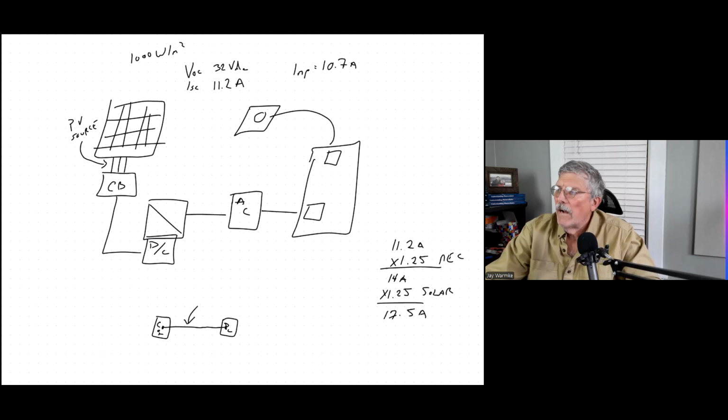Well, it turns out that the panels themselves generally in today's market come with 12 gauge wire. So that wire is going to be able to handle the amp output even with the correction factors. So that's just kind of built into the pie. So that's going to be 12 gauge wire. This wire here, number 12 AWG. And we made our jumpers that way, and now we're going to terminate them in the combiner box.